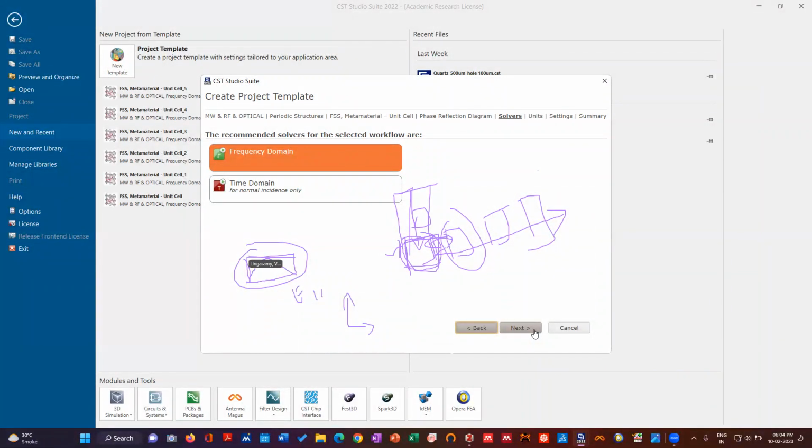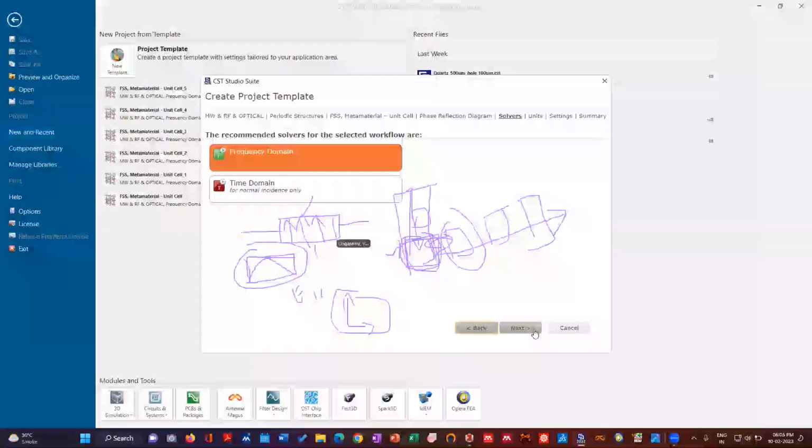So that's how we can make TEM waves. If you are simulating, for example, a waveguide like this, one wall you can consider as a magnetic wall, another wall you can consider as an electric wall. So you will generate the TEM waveguide, which is actually a planar wave only. TEM waves, so transverse electromagnetic waves.